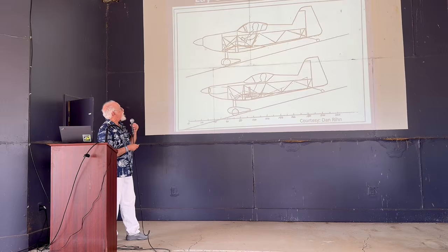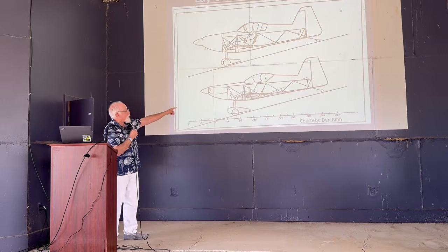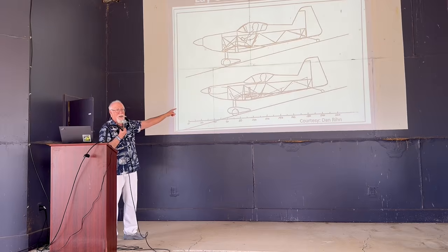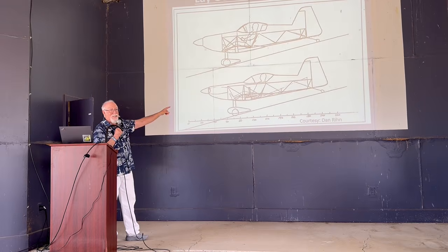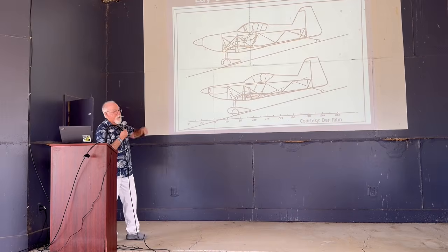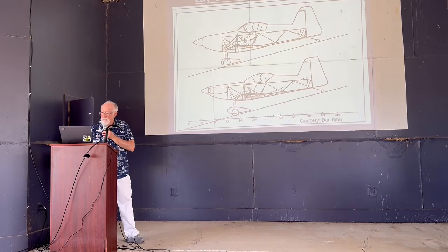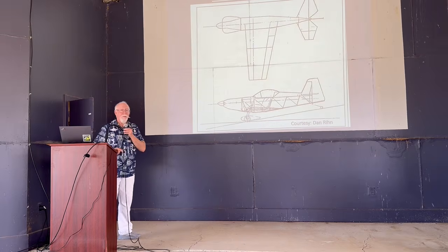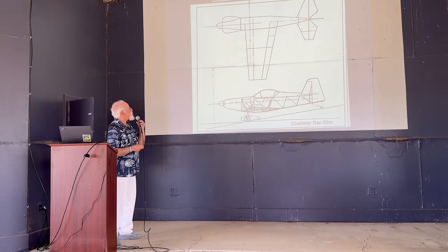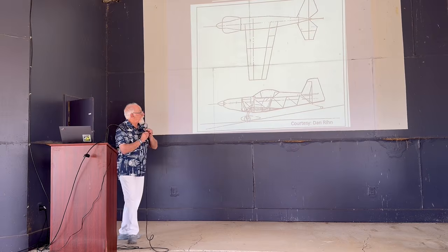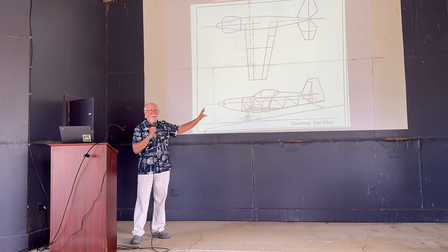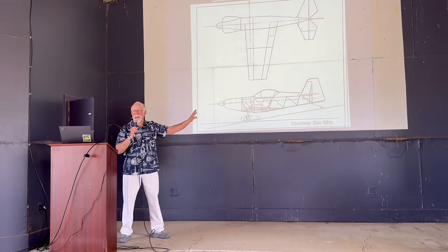He's already getting the pilot in. You notice how he's already got the pilot's knees, the spar going under the pilot's knees. He's figured out the load path, about where the truss goes, about where the engine hangs, right? So having done that, you now start figuring out where the flying surfaces go. If you look at this, you can already recognize the final airplane, but you can also see this is not it yet.